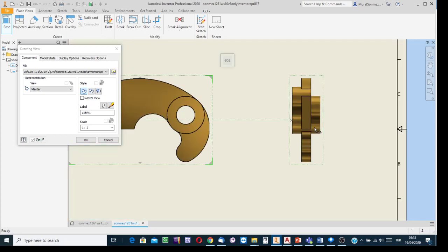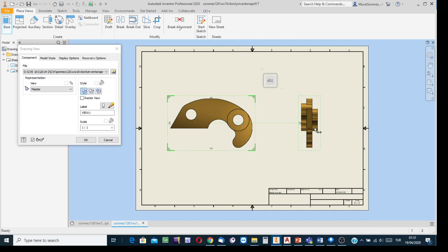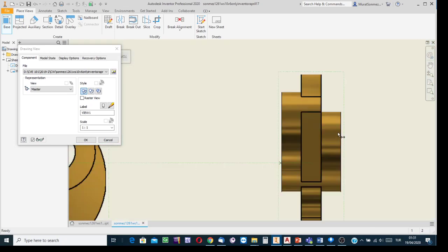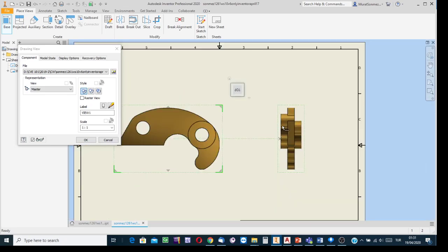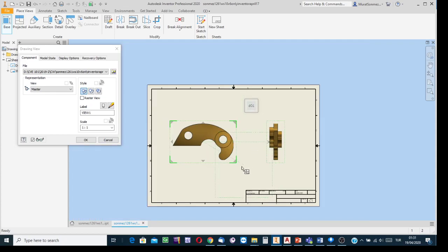But if the left side view won't be understandable, because you see here the boss at the back side and the other boss are in almost alignment, so that view may not be understandable. So create the top side view as well. From the top view, the reader can see that here and there are two identical bosses, and at the back side there is one more boss. So good idea: for the convenience of the reader, create three views.